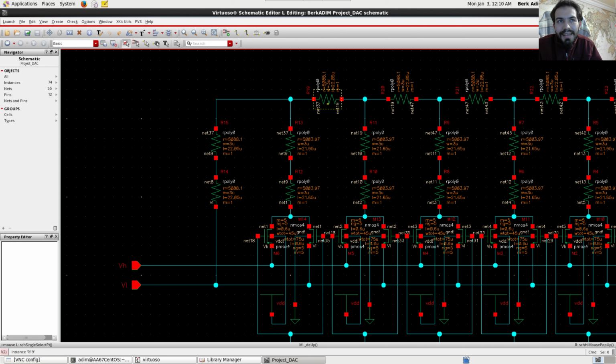You might ask me, quite rightly so, aren't the on-state resistances of PMOS transistors and NMOS transistors different? Well, the charge mobility in p-doped regions and n-doped regions, at least for our process, are different.